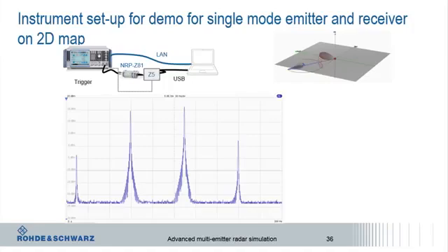If you remember, we defined exactly 4 antenna turns. If you remember, the first antenna turn had a lower power level than the middle ones, and the last one also had a lower power level. The reason again is that the raster scan of the receiving antenna is looking at the emitter antenna under different angles and therefore leading to different power levels. But this is exactly what is happening in reality. The distance between 2 of these peaks is exactly 1 antenna turn. The drop of power level corresponds to the antenna scan type of the receiving antenna and the antenna pattern.